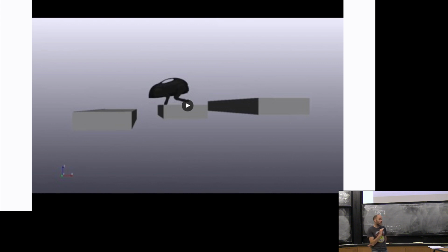So, remember the idea that we had where you could sort of cheat and have force at a distance? That was one way to make the contact planning problem easier. The relaxation: the angular momentum is what kills you here, this R cross F. So instead of saying that R and F have to be exactly on the line R cross F, we say it's going to be in some region around R cross F. That means we're assuming that we could get an angular momentum that may be aphysical. But we can make that as tight as we want, at more cost for the optimization.